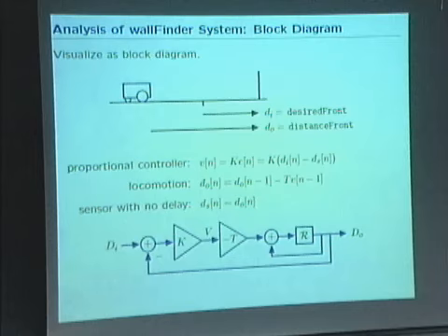So you can visualize that as a block diagram, of course, right? Do you get that this plant model here? It's got a minus 1 here and a minus 1 here, so that's equivalent to having a delay in the forward path. And then it's got feedback because the previous signal is directly put around to the feedback. So this part here is the model of the plant, okay?